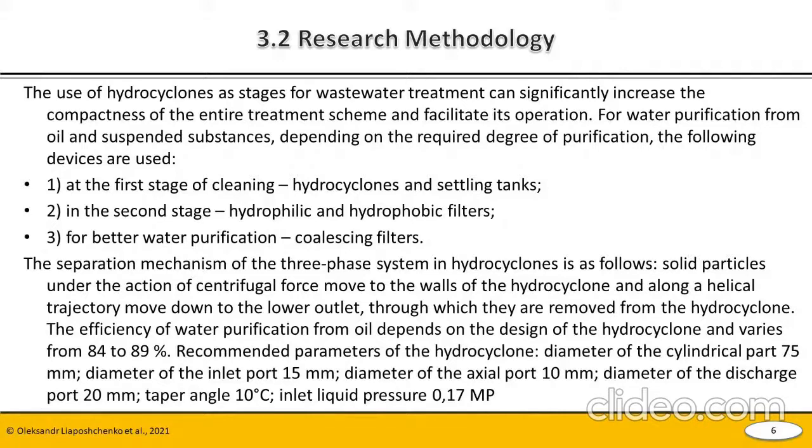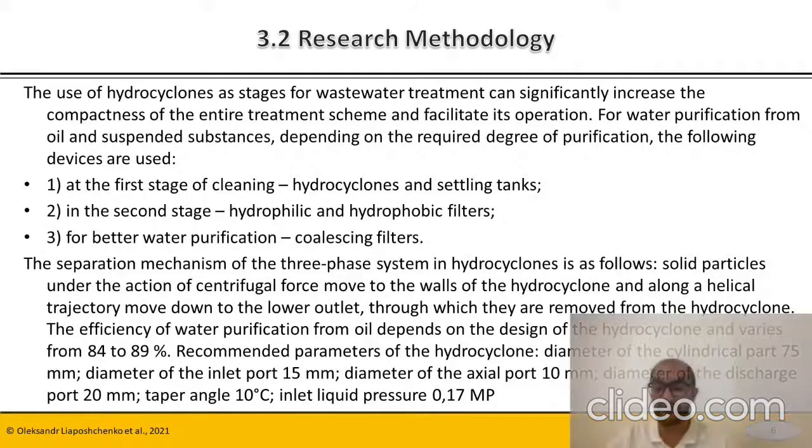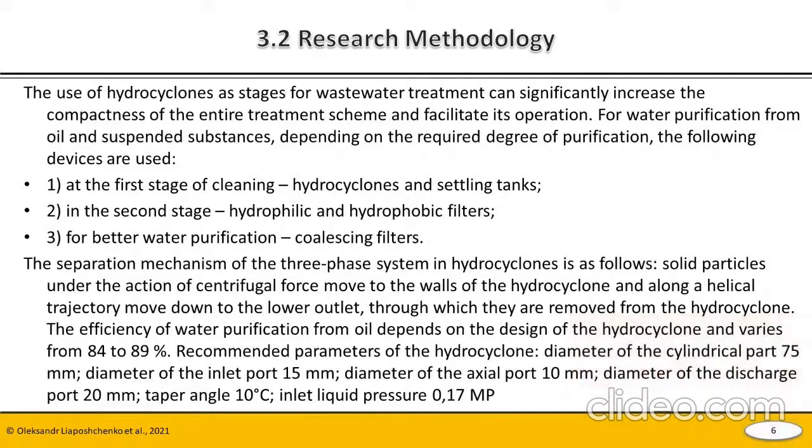The separation mechanism of the three-phase system in hydrocyclones is as follows. Solid particles, under the action of centrifugal force, move to the wall of the hydrocyclone and along a helical trajectory move down to the lower outlet, through which they are removed from the hydrocyclone.